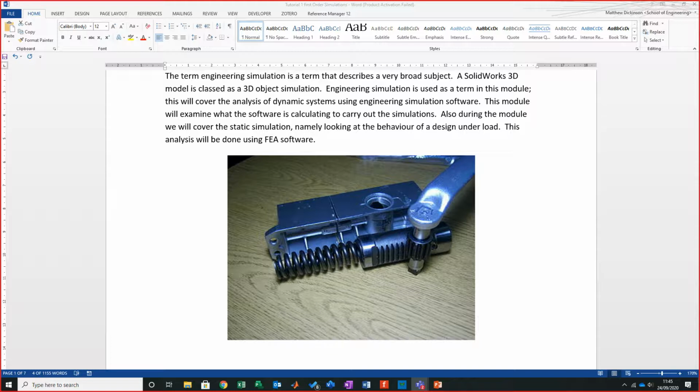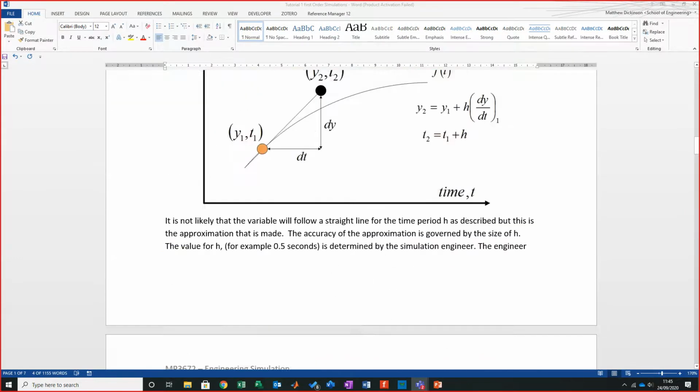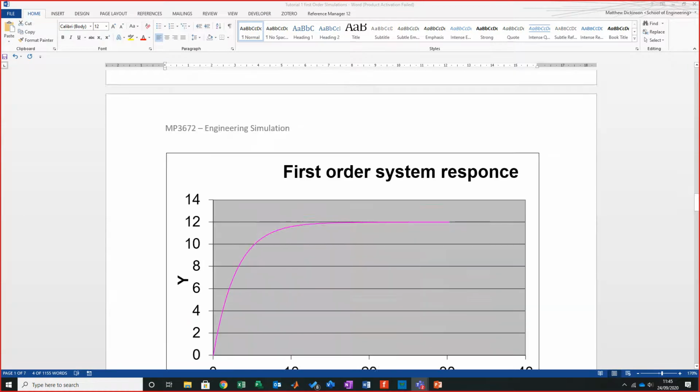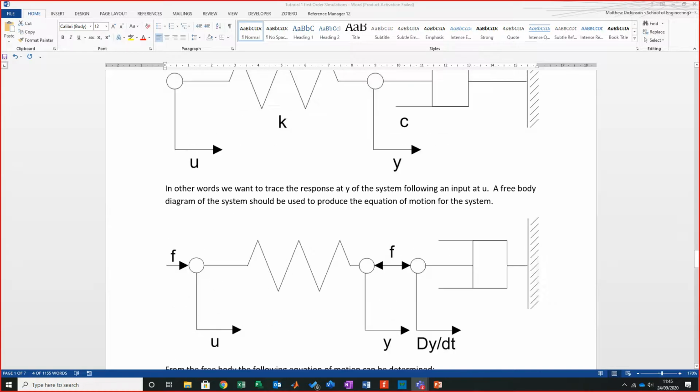Then once it's in that position, obviously it's there to be reloaded. If you incorporate a damper into this, a damper is a dissipation method of force as it's being applied. In other words, you can steadily control the way that it outputs. So if I show this as a plot, these notes are actually on Blackboard, that is the typical motion that you would expect from a spring damper system.